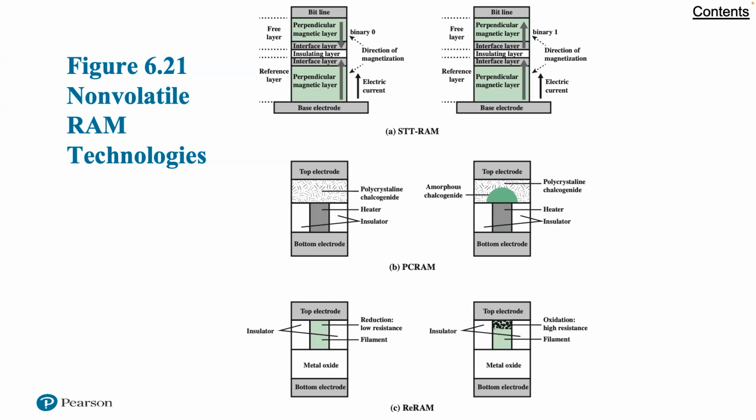It has a low resistance if the magnetization of the free layer and the pinned layer are parallel. In first generation MRAM designs, the magnetization of the free layer is changed by the current-induced magnetic field. In the STT-RAM, a new write mechanism called polarized current induced magnetization switching is introduced.